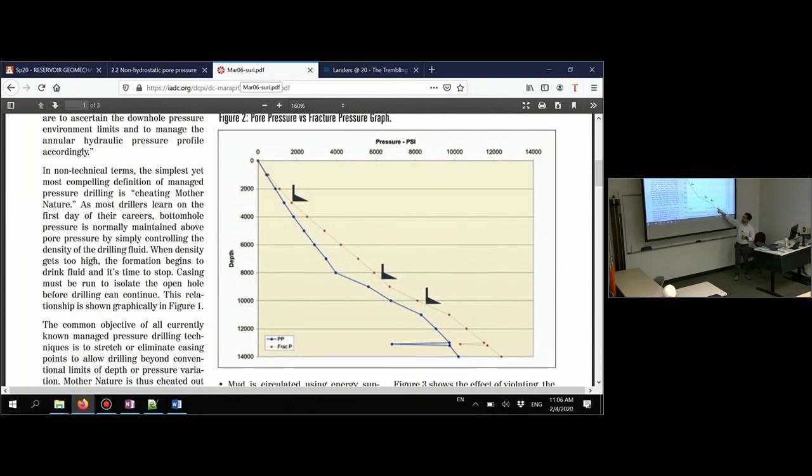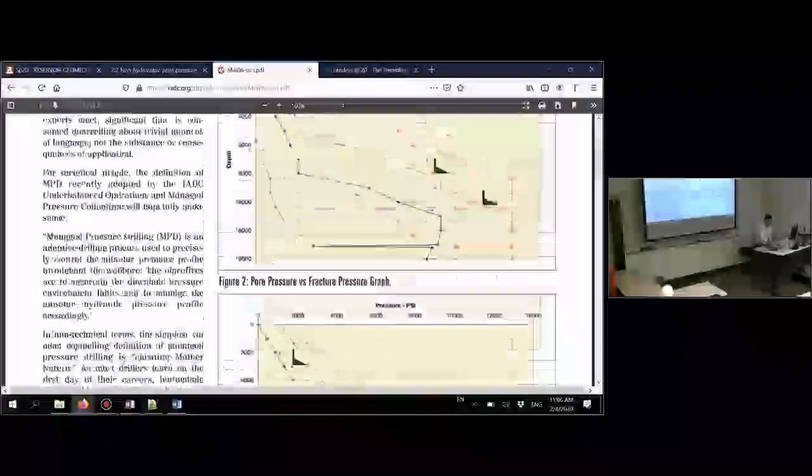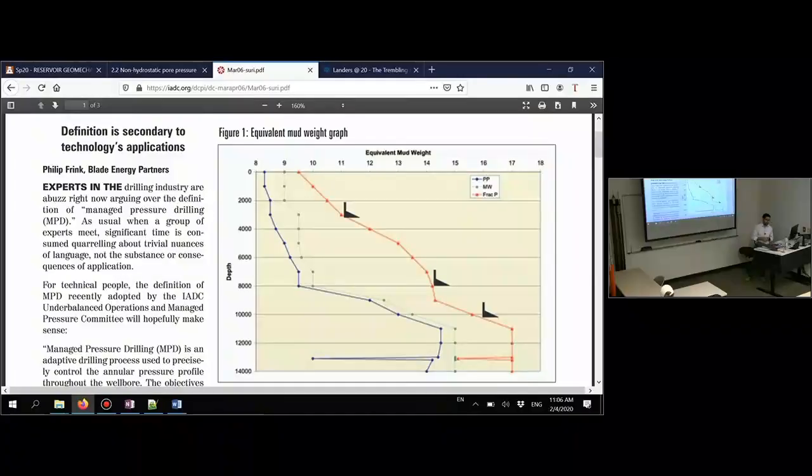And when the fracture gradient goes down very quickly, that's very problematic for drilling, because if we look now at this in equivalent weights for drilling, and we're going to see this later on in detail, guys, don't worry about this, you will see that the available window that we have for the mud weight is this one.